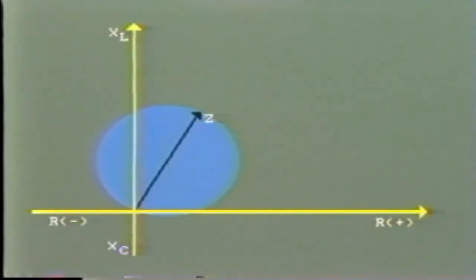The main feature of this relay is that maximum closing force of the relay occurs when the impedance is at a specific phase angle, usually about 60 degrees. This is similar to the phase angle of the line conductor impedance. The result of this characteristic is that as the impedance phase angle changes, let us say becomes smaller, then the unit will operate only for a lower impedance, that is, a higher level of current. This means that it is less susceptible to incorrect operation due to the load impedance, which can cause the relay's impedance to have a very low phase angle down here.